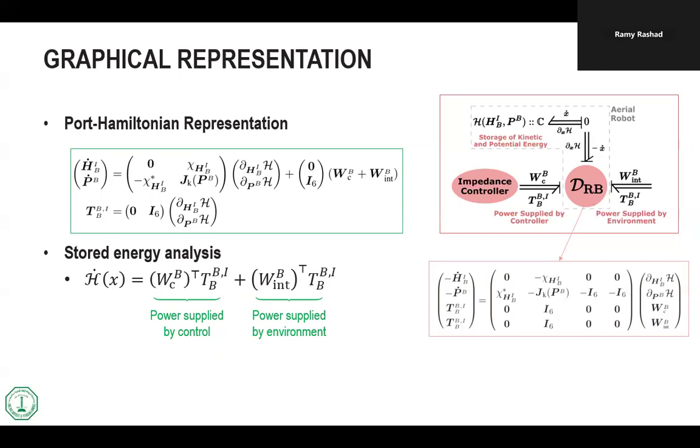You're talking about this big skew symmetric part, or you're talking about the skew symmetric one, which is the J alone, because when we were talking in this form, which is x dot equal to J of x multiplied by the gradient of h with respect to x, this was the J part, which was skew symmetric. Yeah. And then we had here the G and the G transpose. Yeah. What we just did here is that we took all of these and rewrote them into a J, and we took two, these are the G's with the minus, and these are the G transposes, just double them to write it into this form. Okay? It's exactly the same.